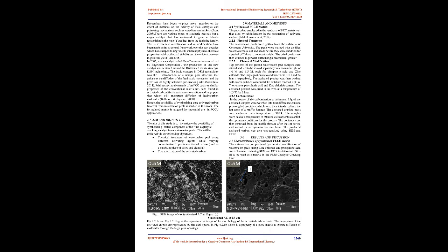The zeolite component makes up 10 to 50 wt% of the catalyst and provides activity, stability, and selectivity. The matrix comprises 50 to 90% of the catalyst and provides desirable physical properties, as well as some catalytic activity (Libby, 1992). Matrices have various physical and chemical properties that make them stand out as components of a fluid catalytic cracking catalyst. The matrix in a fluid catalytic cracking unit is considered as catalyst support, which is usually silica alumina. One of the functions of matrices is to act as a diffusion medium that allows the diffusion of hydrocarbons in and out of the catalyst particles.